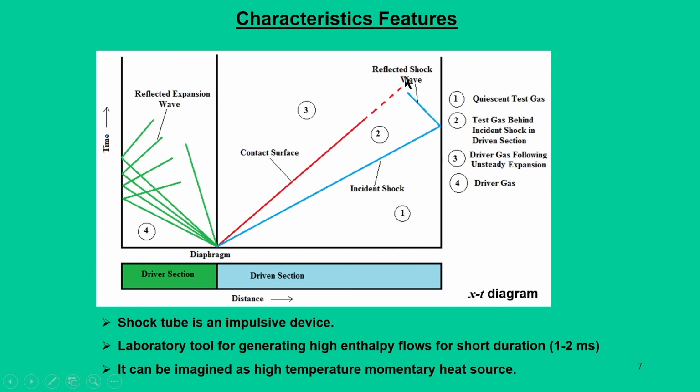And what we see is that we are going to say that your test time is terminated by the arrival of the contact surface. Now, if the test keeps on happening beyond your test time, we can see that the entire gas gets diluted, and mainly because not only does the contact surface arrive, your expansion waves also come and hit the contact surface, or reflected wave.